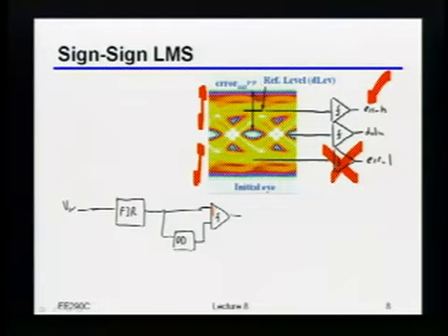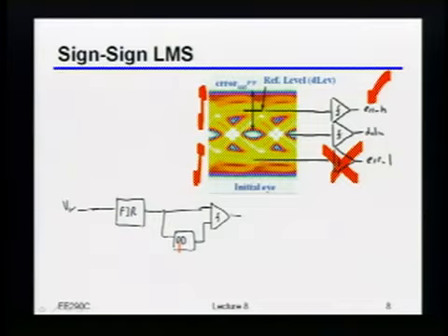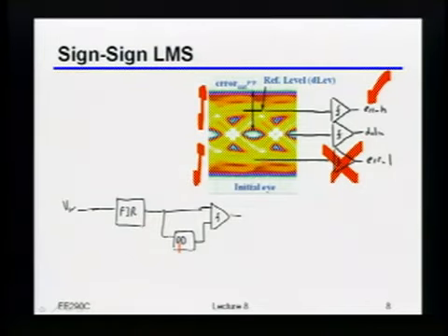Let's say that I want to get this right to within 100 microvolts. Tough, right? I have to build a really, really good peak detector. Maybe it can be done, but it tends to be kind of tough, okay? And by the way, I just added some extra loading onto my high-speed signal path, which, okay, maybe is not horrible, but there's another trick you can play.